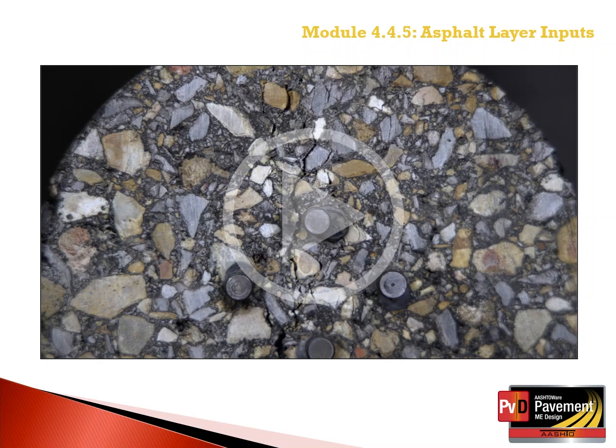The test should be stopped when the cracks start to occur or when the indirect tensile strength starts to decrease to prevent damage to the LVDTs. Or stated differently, the test should be stopped when the load starts to decrease to prevent damage to the LVDTs.